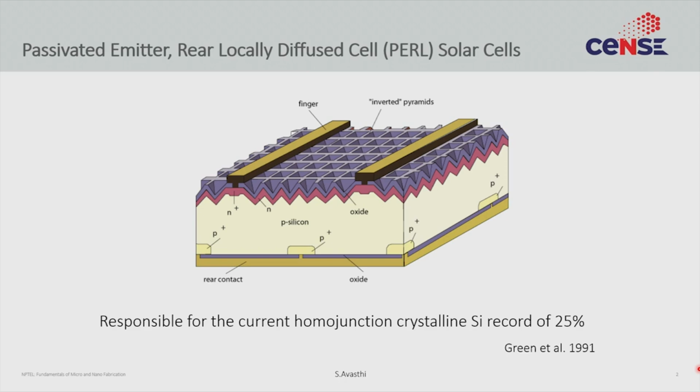One photon would give you an electron and hole, and the efficiency of the solar cell depends upon how many of those generated electrons and holes you can extract out from the device before they recombine within the cell. There are a lot of internal recombination processes that can happen, in the bulk and at the surface, and the goal of a successful device is to make sure that those recombination processes are either very little or don't happen at all.